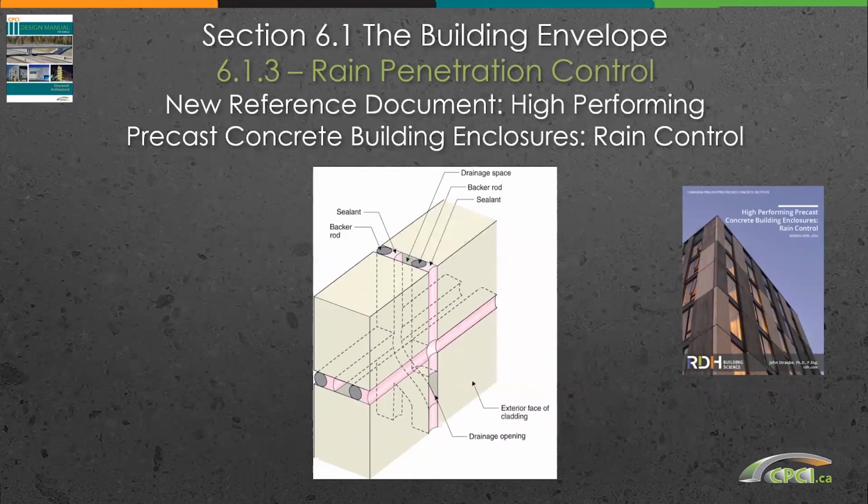Both conventional and insulated panels provide better resistance to rain penetration and air leakage if designed as perfect barrier drained joint systems. The precast concrete is considered as impermeable, and any water leakage is controlled at the joints. The concept of a drained joint system for a precast wall assembly is demonstrated here in this isometric projection.